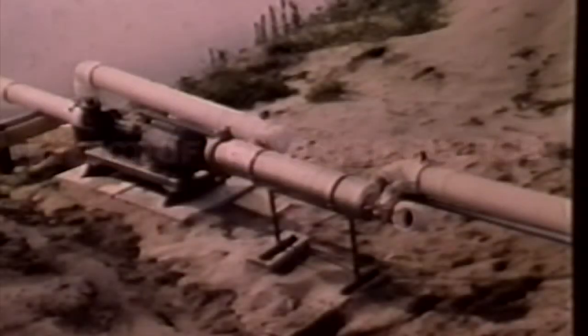Trickle irrigation requires water free of foreign matter. Clogging of emitters is the most difficult problem encountered in trickle irrigation systems. The nature or characterization of the particulate matter that may clog the emitter depends to a large extent on the source of water. All water entering the system requires filtration.